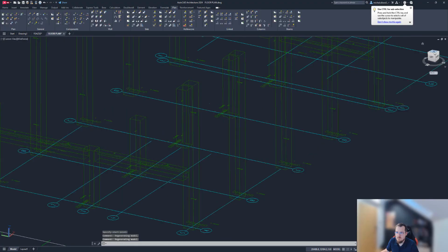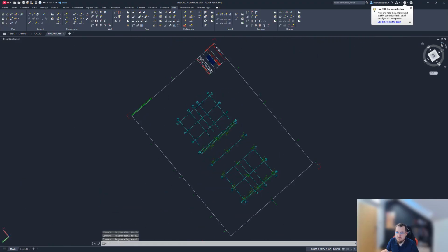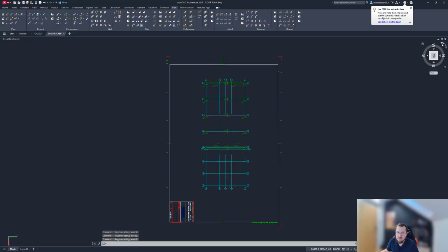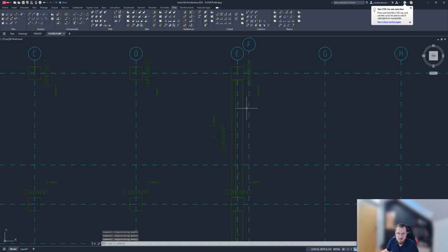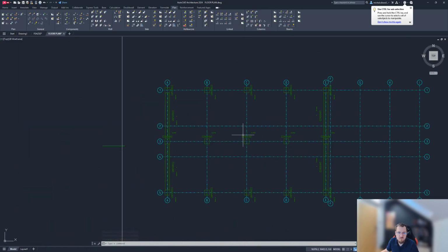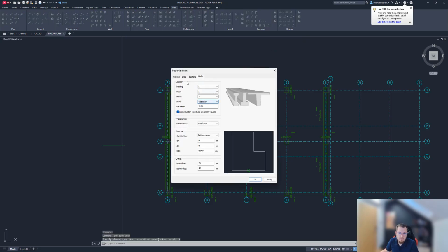Okay, and let's go to the top. You may notice in our view that since lifters are placed automatically in the columns, they're also placed automatically in the beams. So that's very, very convenient for us. That's because of the settings that we have. We have defined casting materials. We have defined the lifts as well. We have defined in the elements basically the way they are placed every single time. So it's easy. We don't have to think about it consciously.